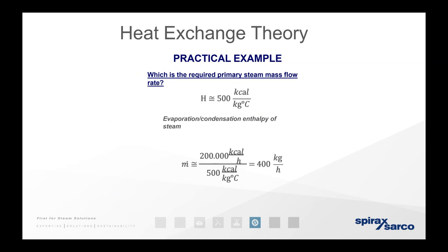Yeah, generally based on the velocity through the tubes. We use it a lot when sizing for turbulent flow because we want that self-cleaning effect. If you've got a low Reynolds number, which gives you a laminar flow, you're not going to get that cleaning effect, and the heat transfer obviously is affected.